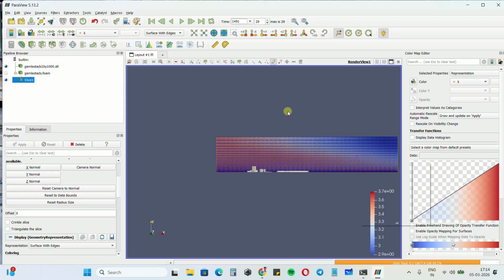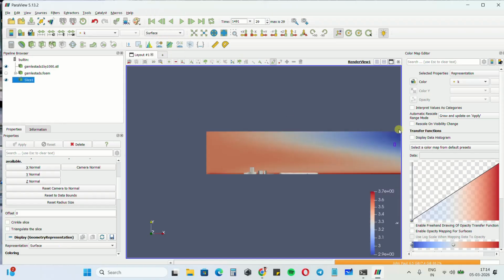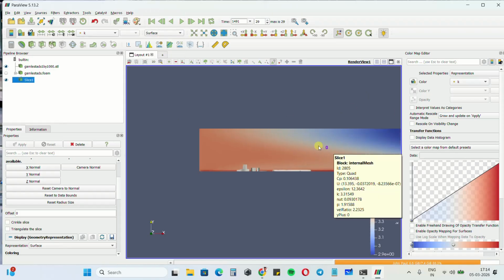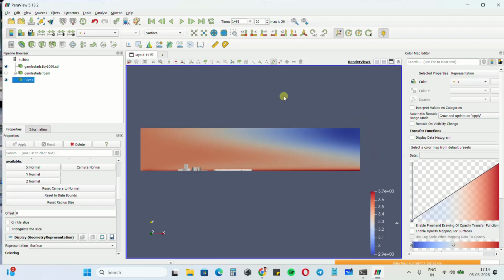In the turbulent kinetic energy plot, again you have a streamwise gradient present in the top right corner, but again what we are concerned about is mostly this region where the incident profiles are most important to us. Okay, so this is fine. We don't have to have horizontal homogeneity in the entire domain, but we need to have it very near the building. Okay, so this is fine.